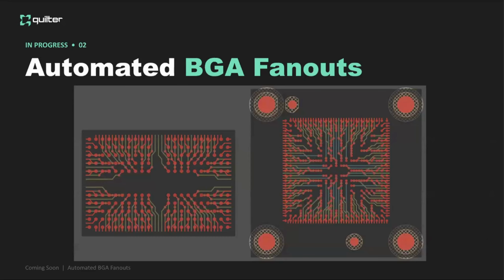Hey, look at that. Yeah, this is actually great because what you're seeing here is an intermediate state that you won't see in the app, where we've pre-computed the best ways to get out of each pin and to the boundary. What you give Quilter is just the footprint itself, and then it's figuring out which way to dog bone and place the via, where to drop down, and then the best way to escape on the correct signal or power layer. And then, of course, throughout the run, the rest of Quilter will hook up to these escapes and trim the ones that were unnecessary.